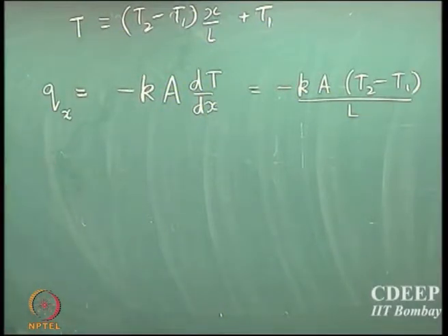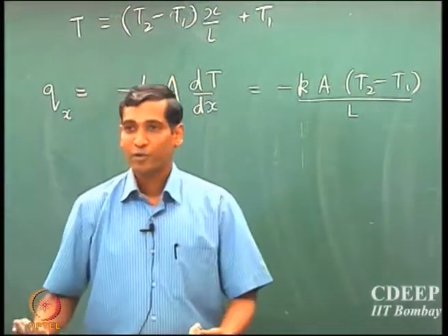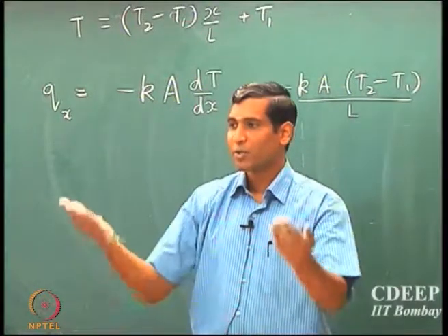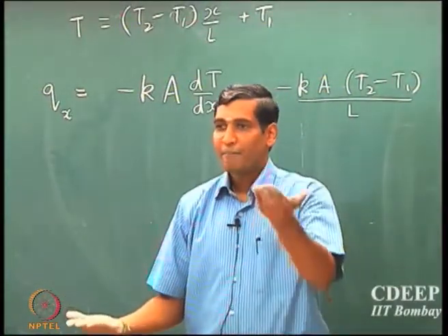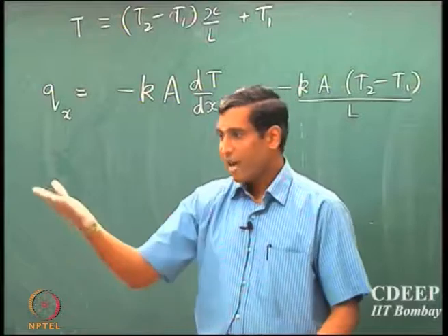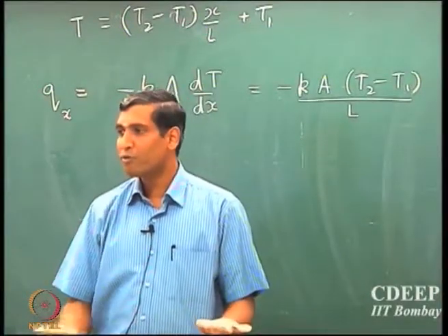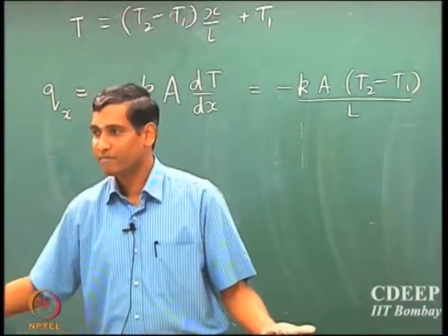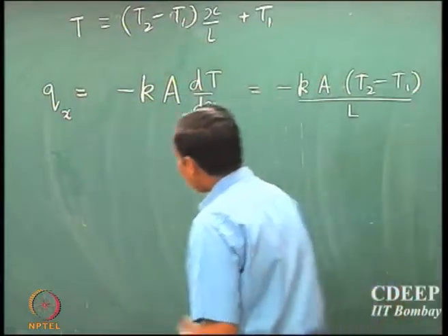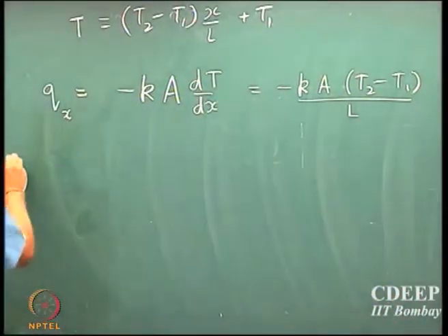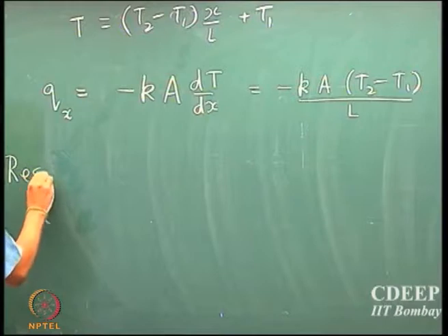Okay. With this framework, we could introduce what is called the resistance offered by the system. We should reflect back on one of the points we discussed a short while ago: what is meant by thermal diffusion? We said there are two competing processes occurring. One is the ability of the system to store heat, and the other is the ability of the system to transport heat because of conduction. One way to look at it is the resistance that is offered.